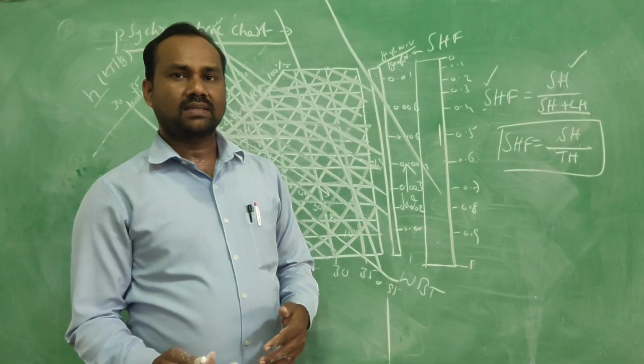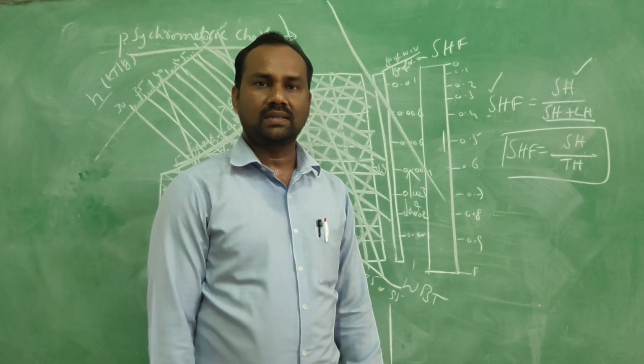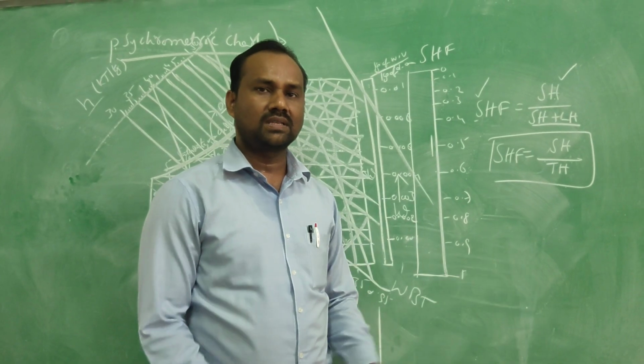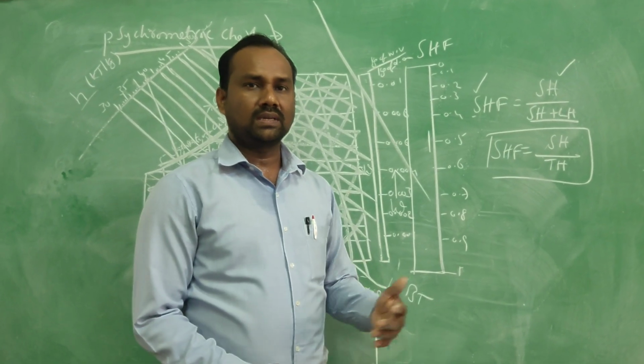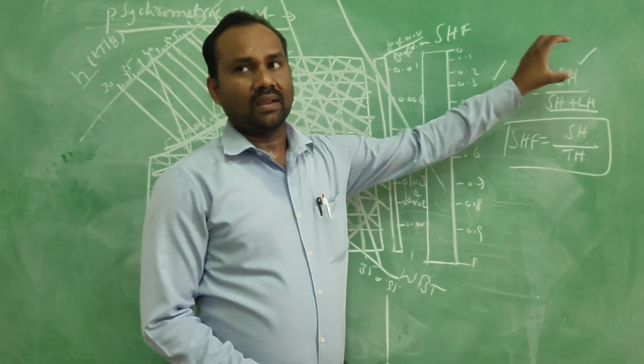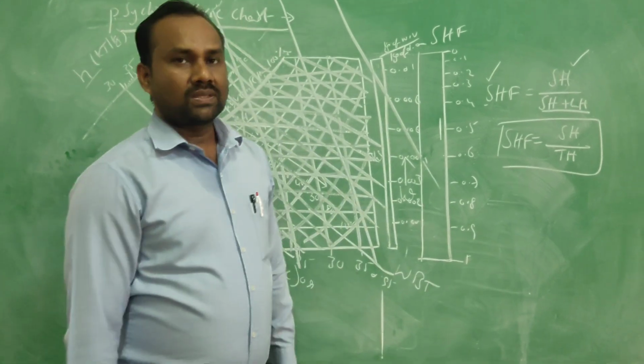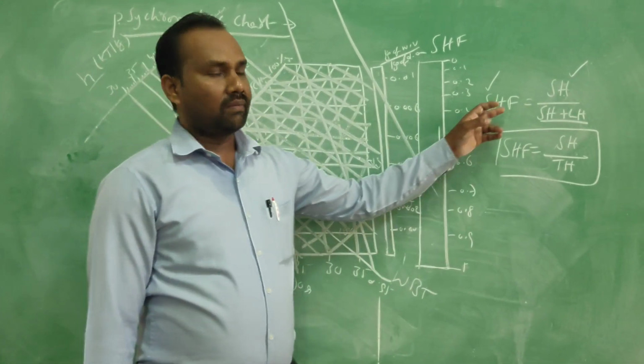When heat addition or rejection occurs, there may be a change in temperature, referred to as sensible heat, or a change of phase, called latent heat. We need to identify and evaluate the sensible heat and latent heat involved in the heat transfer process.